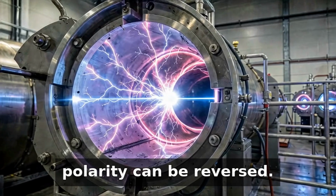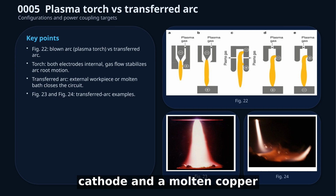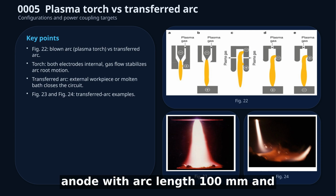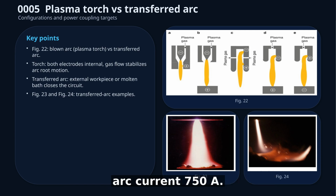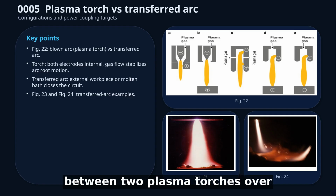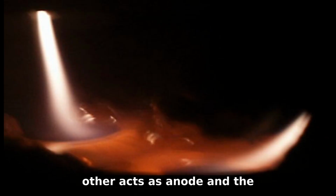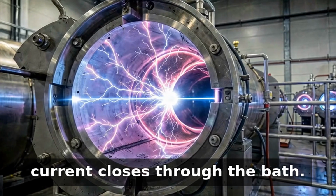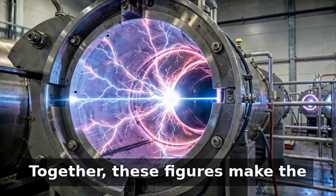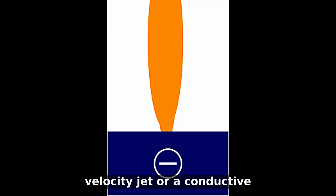Figure 23 shows an Ar/H2 transferred arc between a hot cathode and a molten copper anode with arc length 100 mm and arc current 750 A. Figure 24 shows a transferred arc between two plasma torches over a molten metal bath, where one torch acts as cathode and the other acts as anode, and the current closes through the bath. Together, these figures make the power coupling pathway explicit, whether the target is a high-velocity jet or a conductive bath.